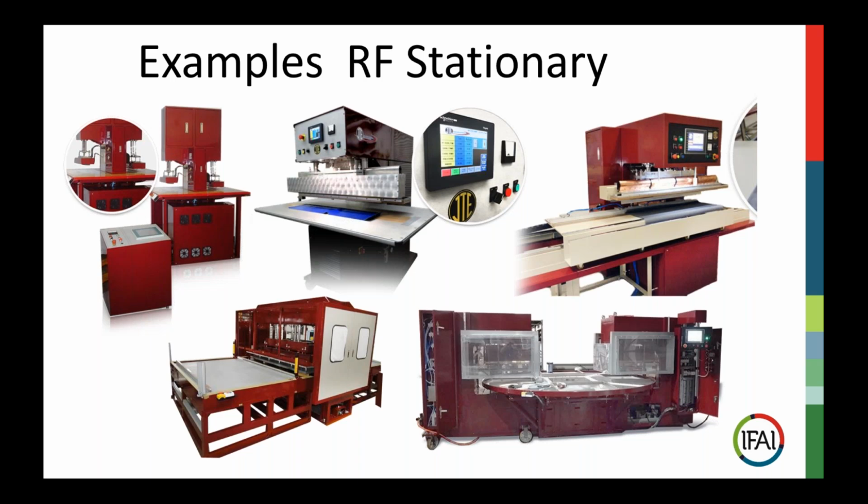But when you're considering an RF machine, it's better to ask, what is the total weld area capable of this machine, rather than what is the kW rating, because this average can vary almost 40%. For example, the average older machine welds 4 square inches per kW, and the newer machines can weld up to 6 square inches.